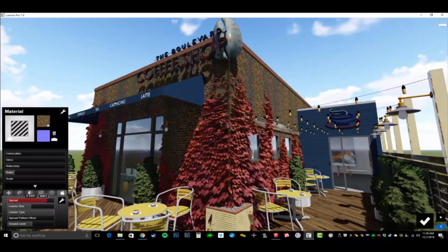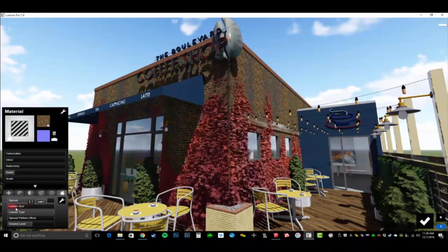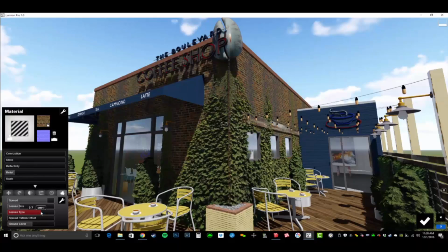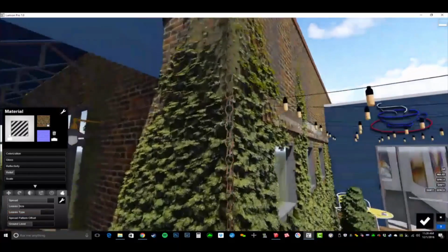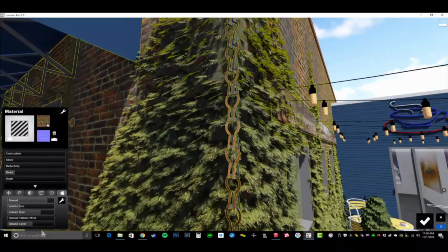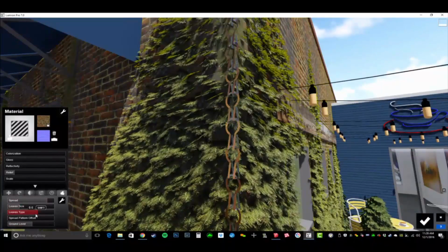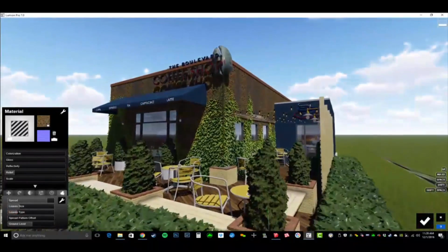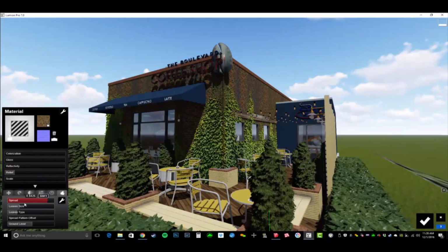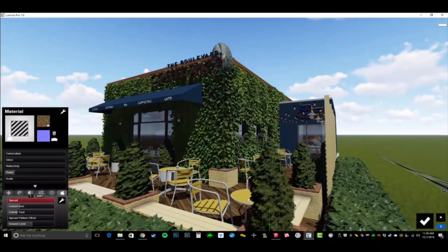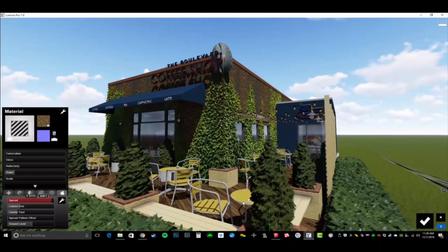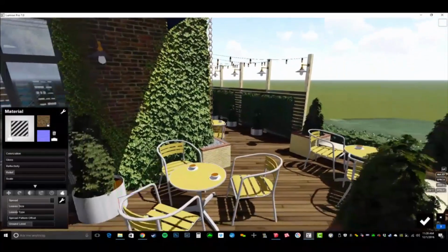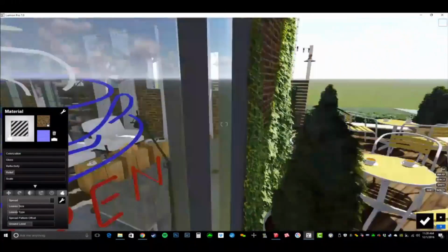Perfect. All right, so remember, if you hold shift, you can slow things down and make much grander gestures. So for this one, I want to dial my leaf size down. I want my leaf type to be, that one's kind of cool. We'll stick with, not the pine needles, but leaf type. We'll go with, yeah, this one looks pretty good. Okay, cool. So you can continue to tinker around with that. Remember, holding shift is what makes it a lot easier to dial in that look that you want. All right, so that looks pretty good. All of our vegetation is really drastically improved in Lumion 7.